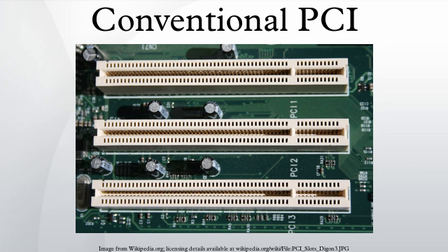PCI Bus Bridges. The PCI standard permits multiple independent PCI buses to be connected by bus bridges that will forward operations on one bus to another when required. Although conventional PCI tends not to use many bus bridges, PCI Express systems use many. Each PCI Express slot appears to be a separate bus, connected by a bridge to the others.